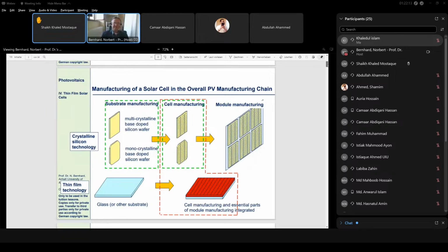Okay, and the second one, how many percent of efficiency do thin film solar cells have? I mean, as I showed in this diagram, it varies from 10% for amorphous silicon to 20% for cadmium telluride or copper indium gallium diselenide. I mean, this would be already volume production efficiencies. To more than 40% under concentration for the gallium arsenide-based semiconductors.